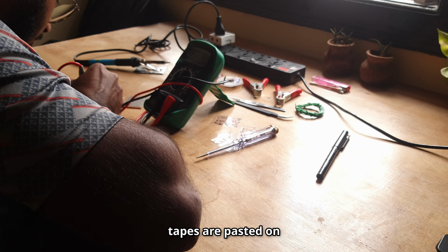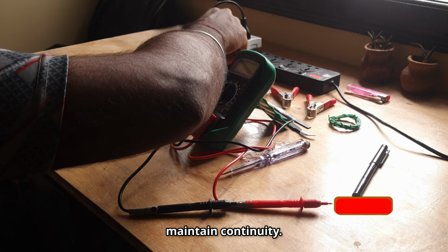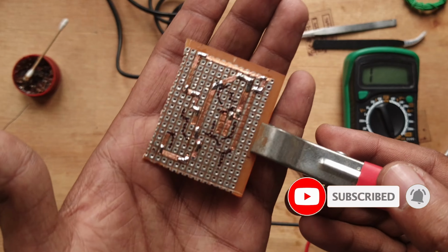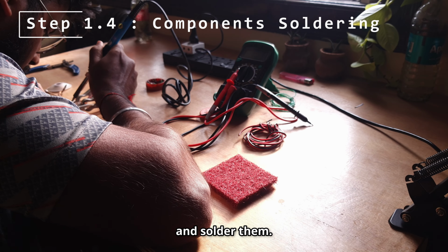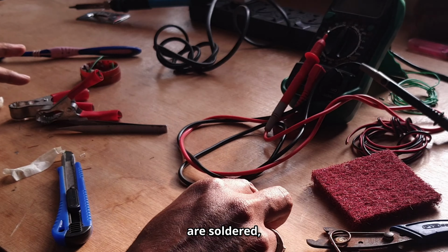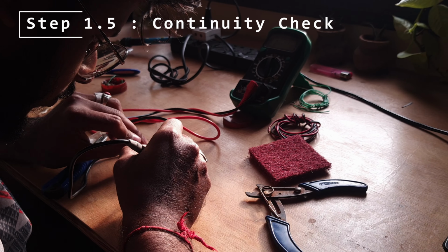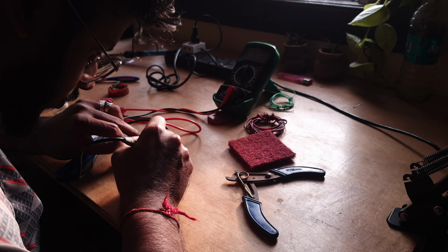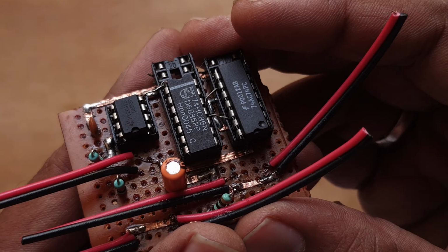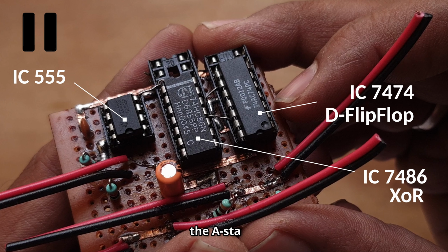Once the copper tapes are pasted on the perf board, the corners and joints need to be soldered in order to maintain continuity. And finally, we need to assemble the components onto the perf board and solder them. Once all the components are soldered, I am using a multimeter to check the continuity of the circuit. Here, IC7486 is the XOR gate and IC7474 is the D flip-flop, while IC555 is used to make the astable multivibrator.